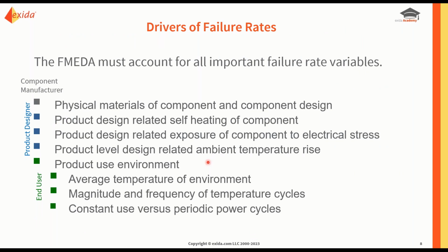So the FMEDA must account for all important failure rate variables, and the drivers. There are 2 main drivers of these failure rates. We have the design strength, which is comprised of the physical materials of the component and component design, the product design related to self-heating of the component, the product design related exposure of component to electrical stress, and the product level design related to ambient temperature rise.